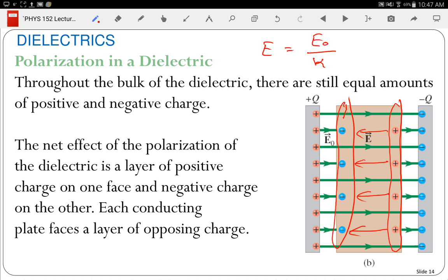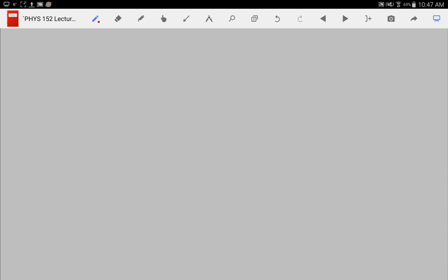Well, how do you make a 1 farad capacitor? It either has to be huge or you have to have a really good dielectric. And so you put in that dielectric and you can make it smaller. The second thing is it allows you to put larger voltages on it because it's increasing the dielectric strength. So there are two advantages that work together.